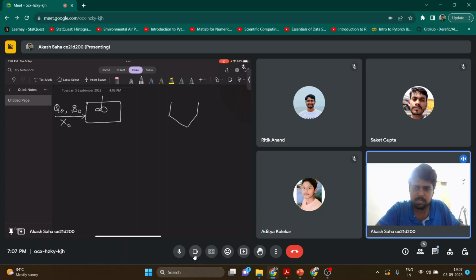Regarding the aeration chamber, suppose the volume is V, the substrate concentration is S, and the biomass is X. We measure biomass in terms of MLVSS, that is mixed liquor volatile suspended solids. In any continuous reactor with aeration, whatever the final effluent concentration is will be carried forward to the settling chamber.